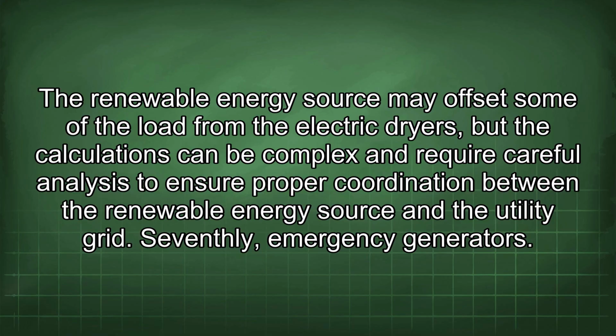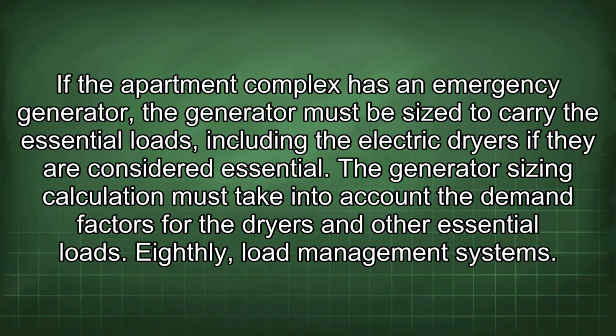Seventhly, emergency generators. If the apartment complex has an emergency generator, the generator must be sized to carry the essential loads, including the electric dryers if they are considered essential. The generator sizing calculation must take into account the demand factors for the dryers and other essential loads.